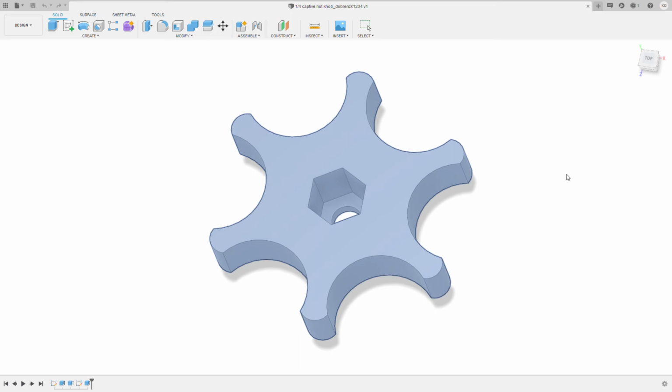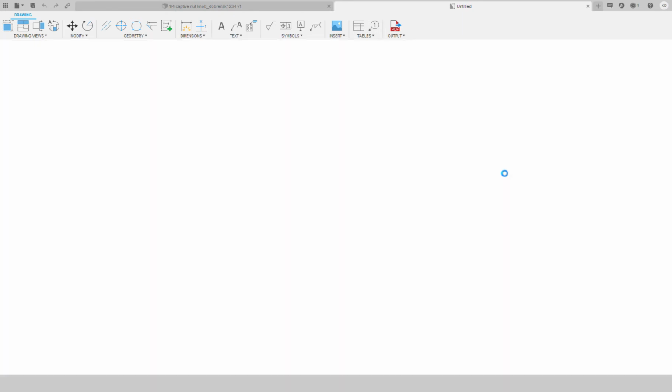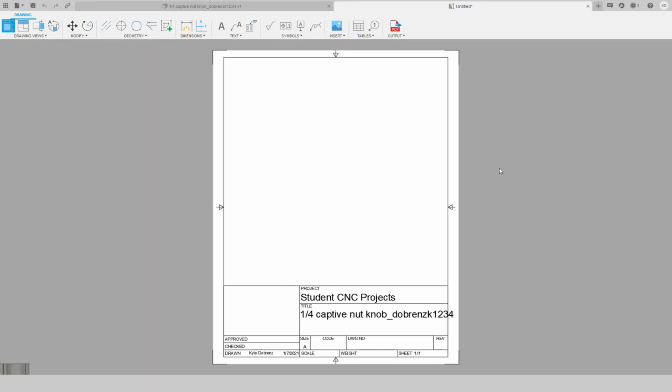For our class, just beginning, we're going to be using A-size sheets. Now, if you notice, these are 8.5 by 11 and vice versa. Well, this is just standard printer paper, so it actually makes it really easy for us to print these out if we need to. And for simple things, this is what I use in class, and this is what we're going to use right now. There's two different ones, because one's portrait and one's landscape. I believe the first one's portrait, and that's the one I'm going to use today. Click OK, and now it's going to open up this sheet.